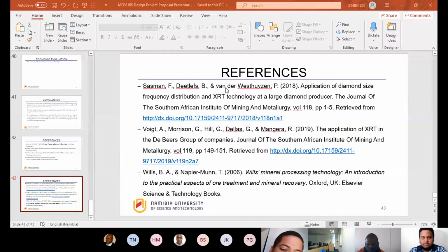As I have mentioned, with the test work that needs to be carried out, we would have to do a mineralogical characterization to see what types of elements we have within this ore of ours, and thus it will give us an idea of what type of flocculants and coagulants we will be using according to the slurry that will feed to our thickener.